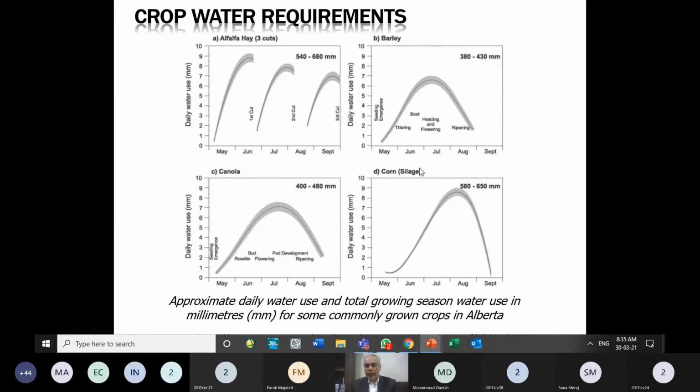The other crops which we usually see over here also, corn or wheat, initially have very little requirement. Then this is the growing or development period. Then it has a maximum requirement when it is fully nourished, when it gains full height and its leaves are fully grown, then its evapotranspiration requirement is maximum. Then it goes towards the ripening phase, and that is the typical way the crop water requirement changes during the growth period of the crop. Similarly, you will see for most crops, only this peak requirement will change. Initially they need less, finally less.